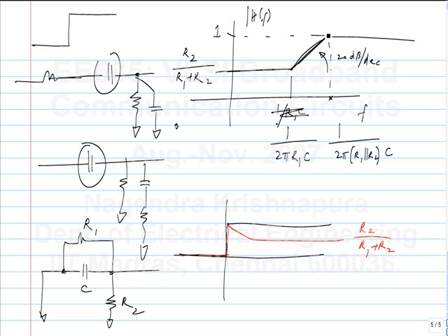That is the rate of transmission divided by 2. So that's where you want the boost also, right? Before we said that to have faithful transmission, we should preserve the frequencies up to roughly Fs by 2. So you should arrange it so that this boost occurs within that. So once you have that, then you will have equalization with something like this.